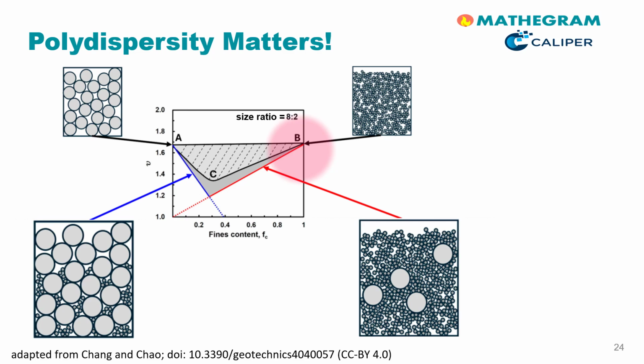As you will see from the counting of particles, the number of small particles to be tracked is substantially larger than that of the large particles. As we have already heard at the beginning of this unit, this suggests to group particles to so-called parcels to reduce these computational entities to be tracked.